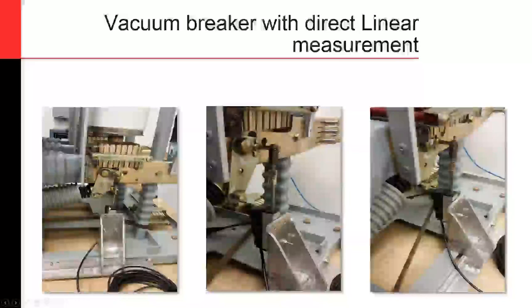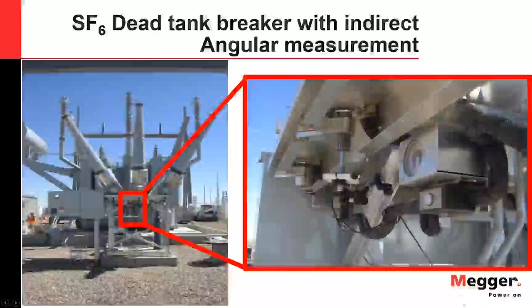This is an example of a vacuum circuit breaker where now we have this little direct connection down on the right below one of the poles. So this is on the outside leg there. So once again, it's gang operated, but this manufacturer puts this little tab so you can hook directly to it and, as that vacuum bottle actuates up and down, your transducer will go up and down, and you're getting the exact stroke of that vacuum bottle there.